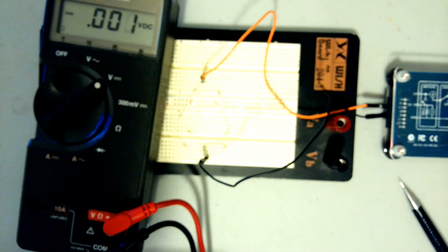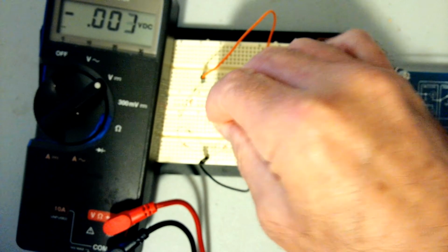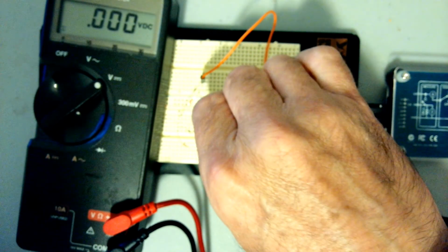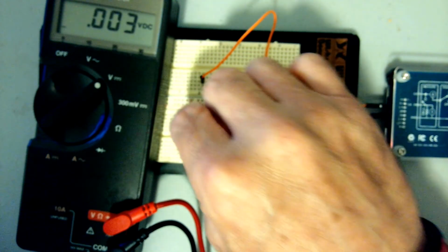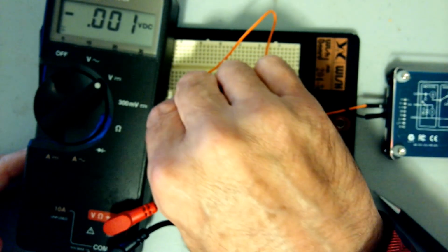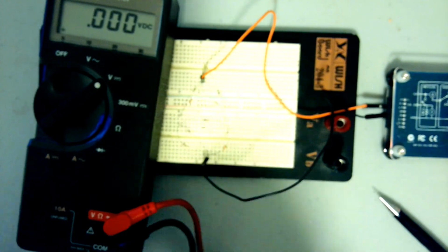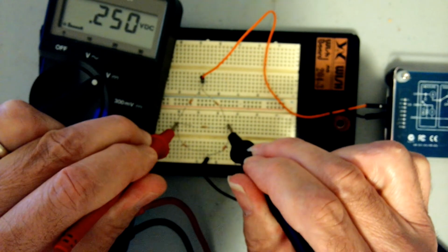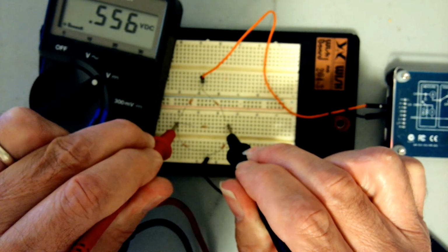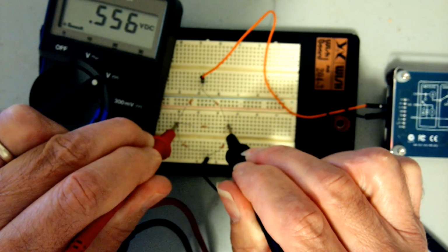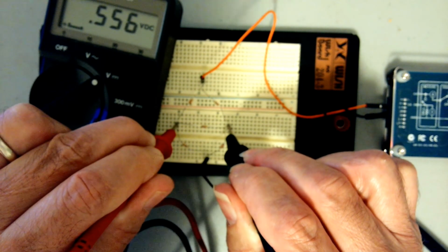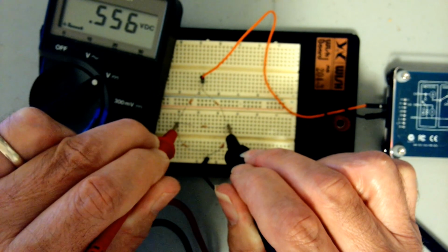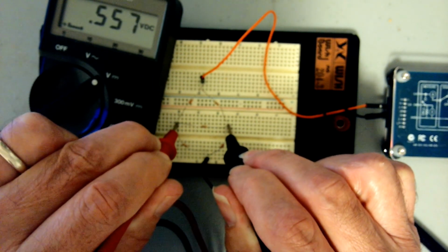And now that was our Thevenin voltage, 0.9. Now I'm going to replace the load resistor here, and we're going to measure across the load resistor: 0.556. We had 0.55, and I did a simulation. It comes out about 0.553 because we did a little bit of rounding off in there. But there's our solution to our circuit.